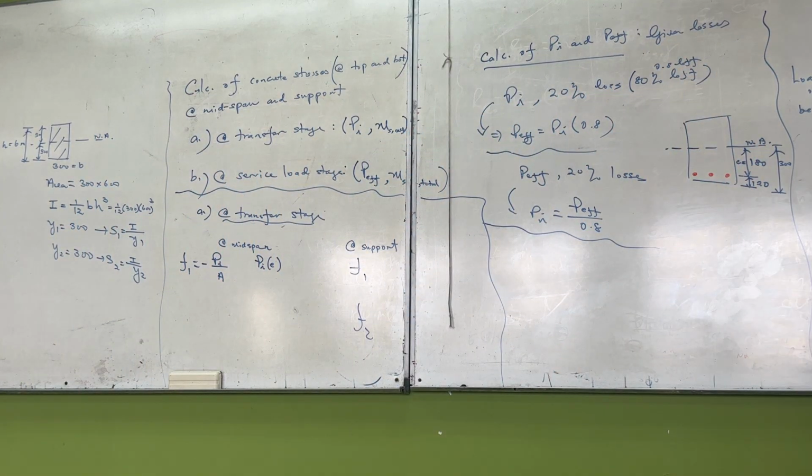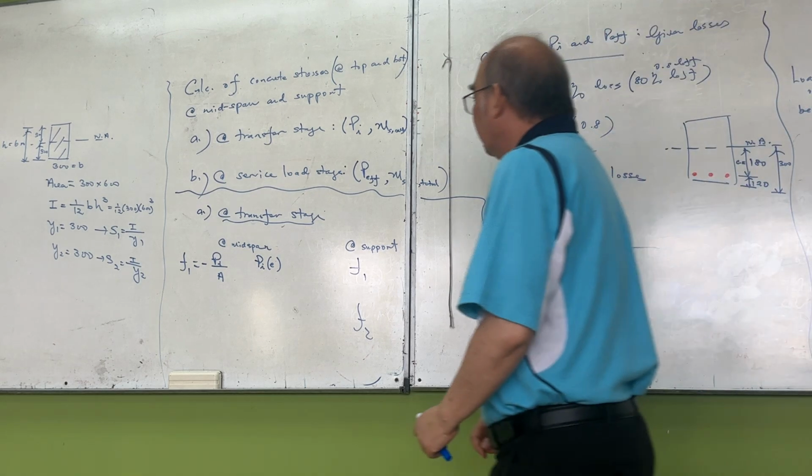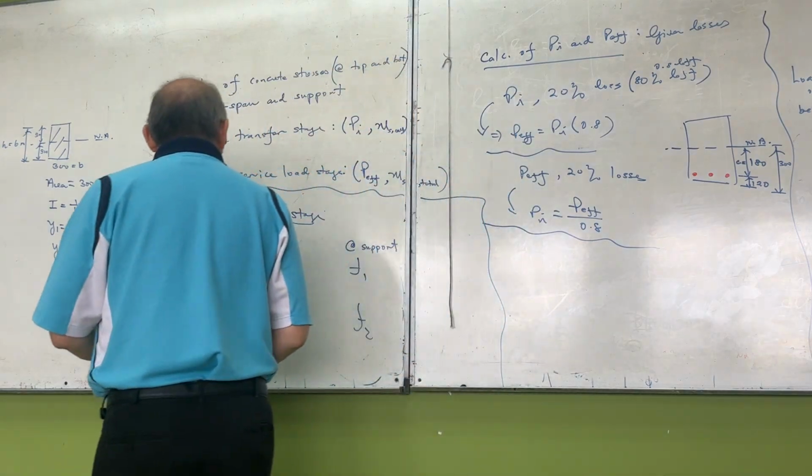One more time. Let's say I use this one. If my pre-stressing force is acting in the middle, there's only pure compressive stress. As soon as I start moving it, then I induce a moment. Understand? So that is why.